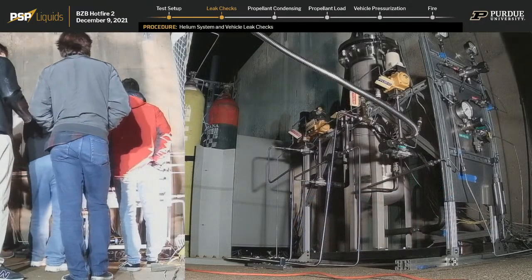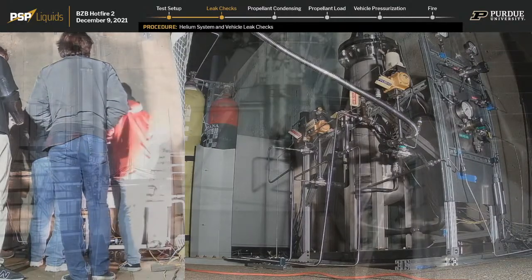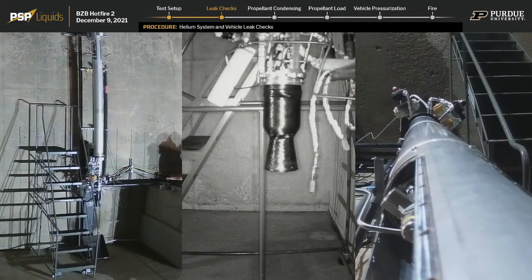Right now, we are of course debugging the BCLS system. Is there anything you want to talk about in terms of the overall rocket? For example, some of the manufacturing challenges we had, or how it's mounted to the I-beam itself? I can go into one of the manufacturing challenges we had on the rocket. Building a common bulkhead rocket has a couple of design decisions that go around it. Because the tanks of our rocket are also the skin, you have to route plumbing connections either through or around the outside of the rocket. And we really wanted to minimize the drag forces on the vehicle.